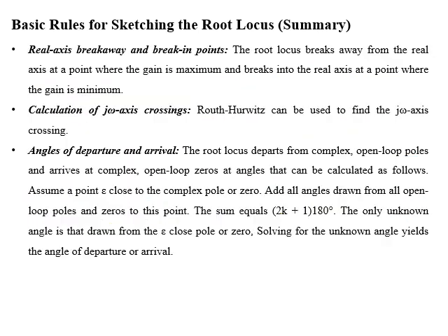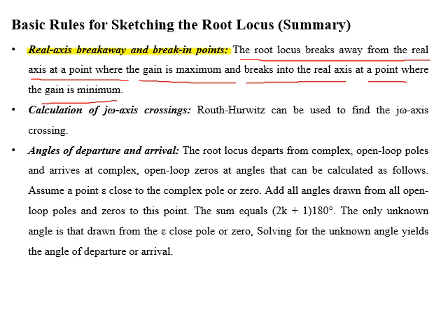Dear students, next is real axis breakaway or break-in points. The root locus breaks away from the real axis at a point where gain is maximum and breaks into the real axis at a point where gain is minimum.